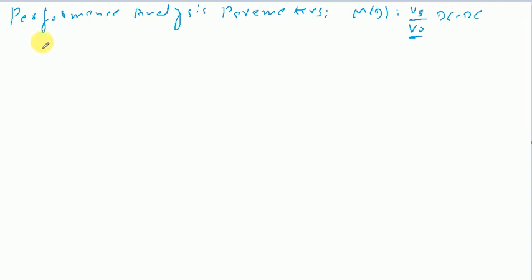And further in the three-phase, we'll have these categories of half and full wave as well, or controlled and uncontrolled. So we need to determine the reason why, if a half wave rectifier circuit can do a certain job, we need to switch to a full wave rectifier circuit, or even to a three-phase rectifier circuit. And if all of them are doing the same job, then what is the difference? These performance analysis parameters will let us know what the difference is.